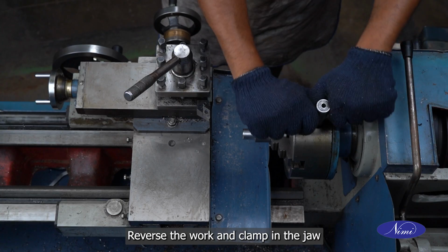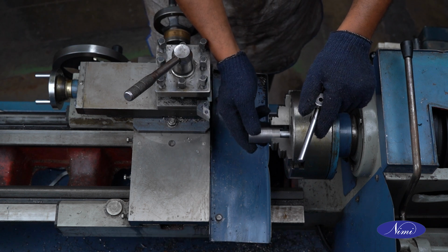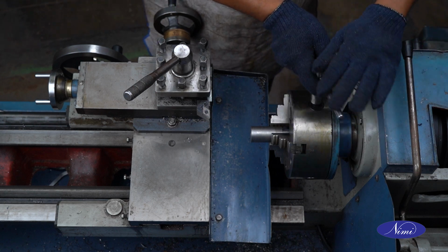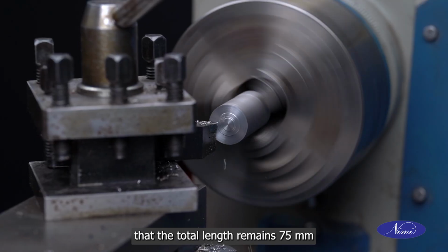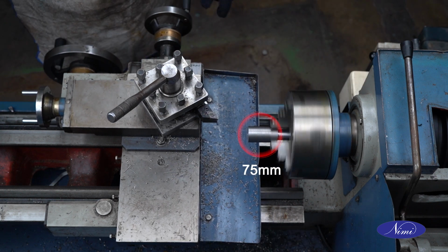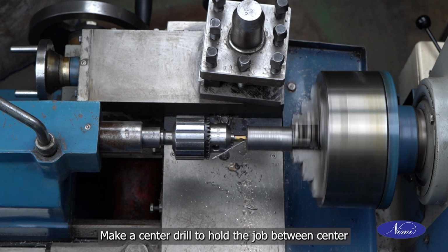Reverse the work and clamp in the jaw. Perform facing operation and ensure that the total length remains 75 mm. Make a center drill to hold the job between centers.